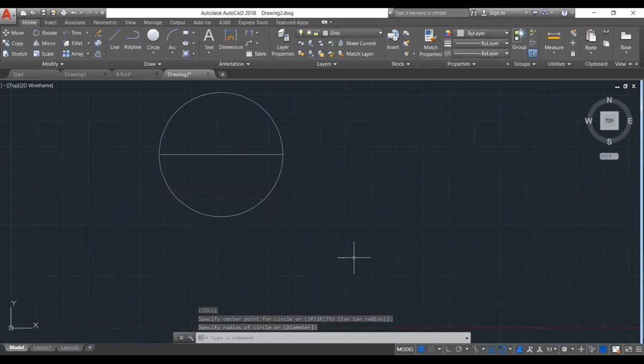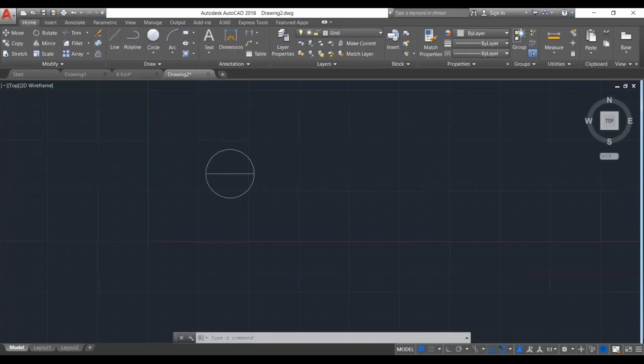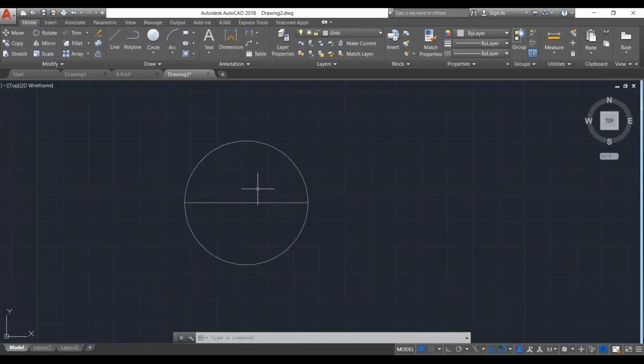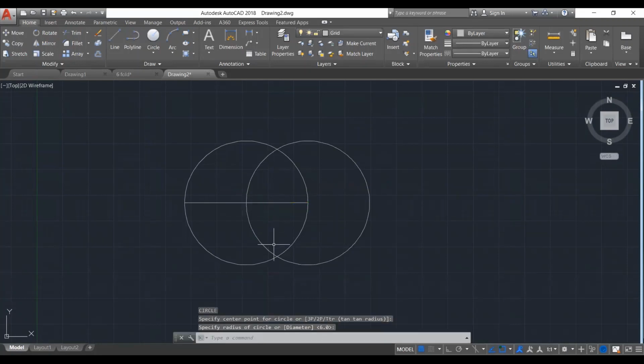Now you can draw a line and you can draw a circle. Using only these two orders, you can draw anything. So I can divide this circle the way we did using the compass. I will put the compass here, at the end point, and open it here. So now these are the arcs, and the same on the other side.